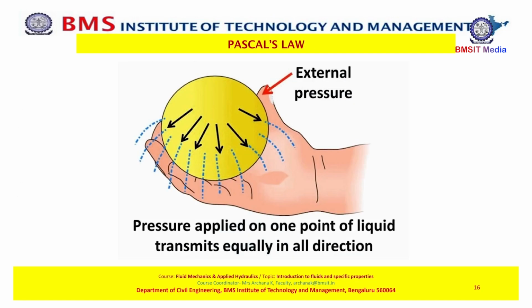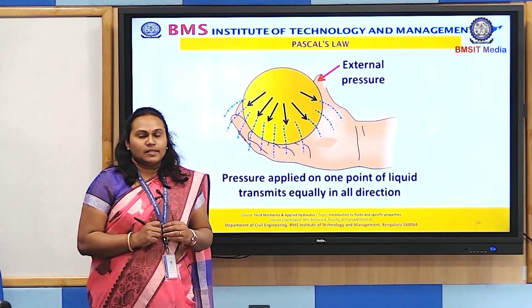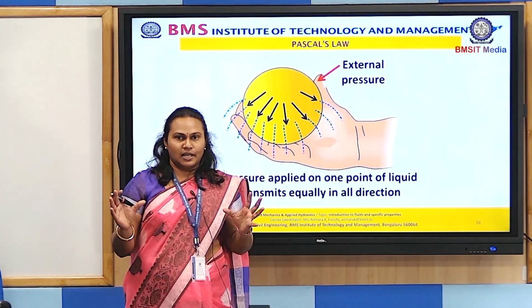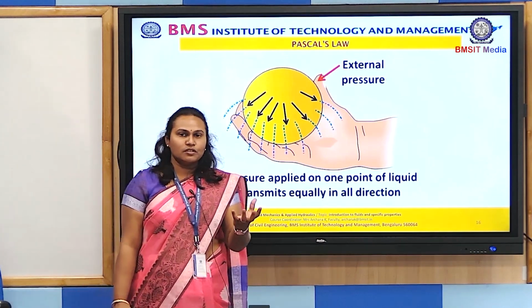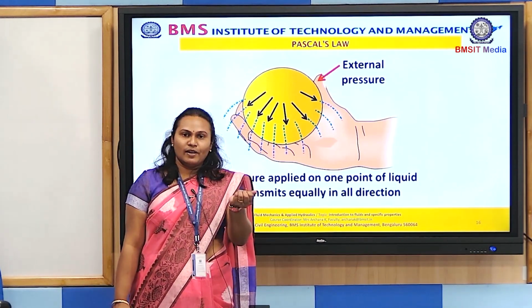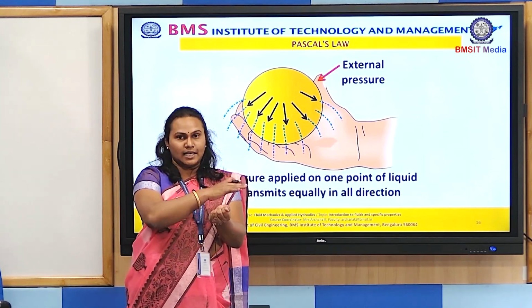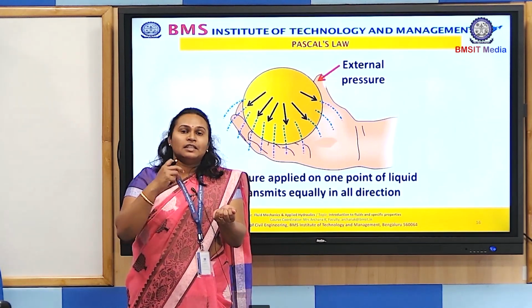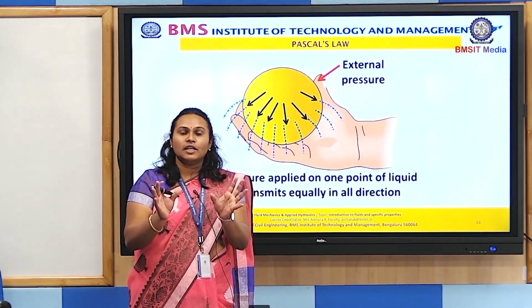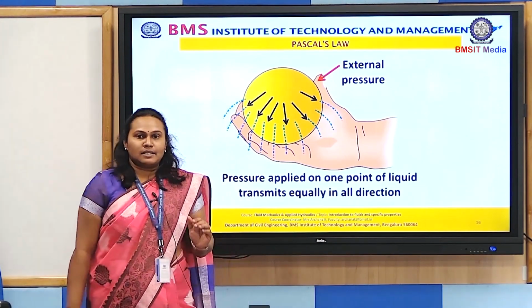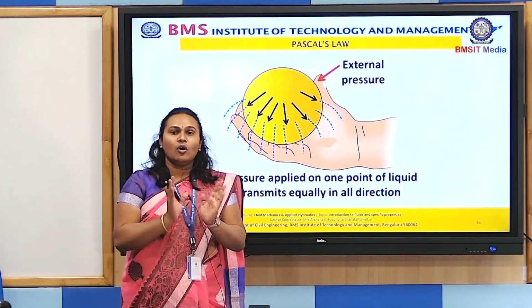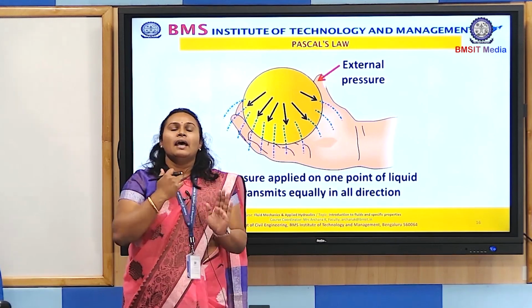So coming to this, with this kind of a basic, we will understand what is Pascal's law. Pascal's law states that the fluid pressure exerts the same intensity of pressure in all directions. For example, if you have a sponge filled with water or soaked with water, and when you press, the water will squeeze out in all directions. It will not only squeeze out in x direction or y direction or z direction. That means water will exert out in all directions. In other words, Pascal's law states that the intensity of pressure of the fluid at rest is equal in all directions, that is x direction, y direction and z direction.